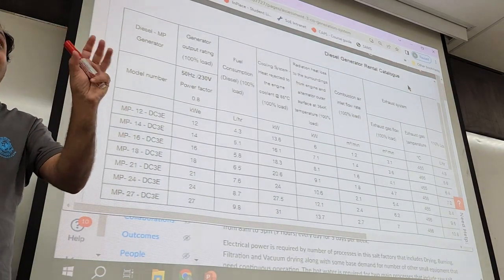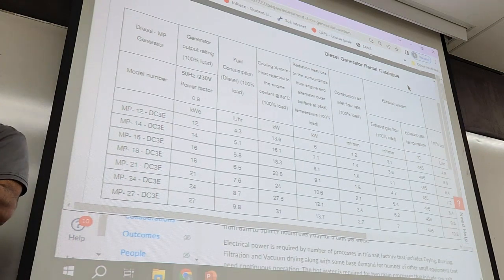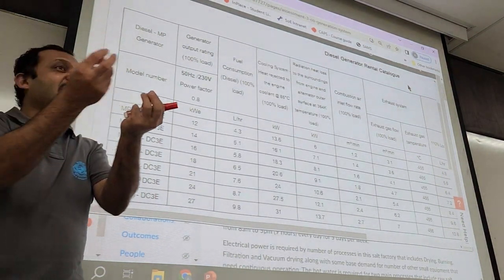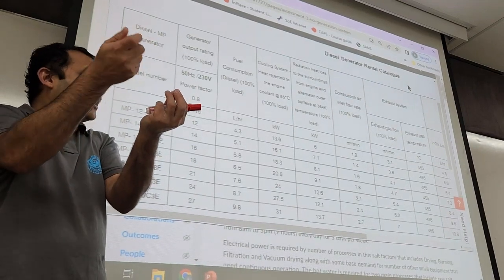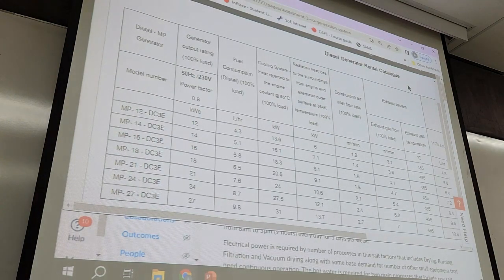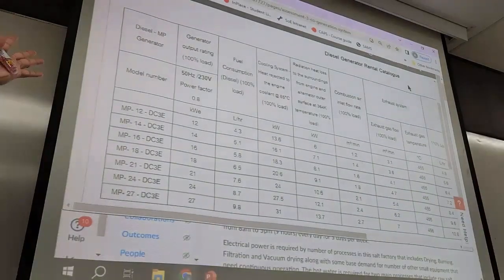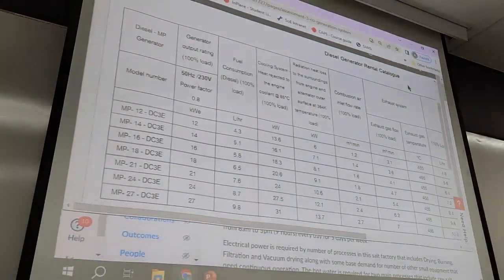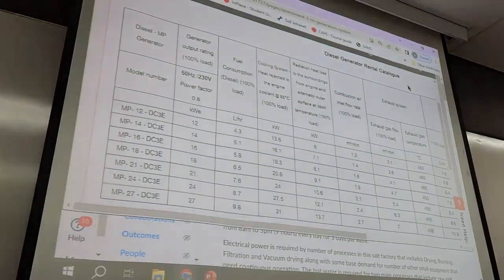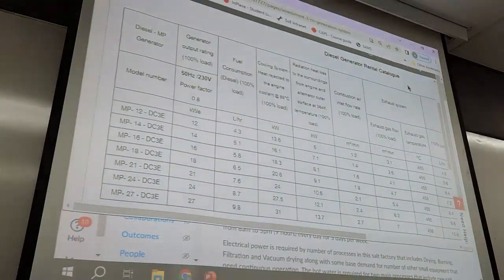Now moisture, water vapor. If you cool down the exhaust to 20 degrees, what's going to happen to the water vapor? It will condense into water droplets, and the nitrous oxide, NOx, dissolves in the water to create nitric acid. And nitric acid will start corroding your heat exchanger. Everything will be rusted. Not immediately, not in 1 second, but after 6 months, the whole heat exchanger is destroyed. And you don't want that.